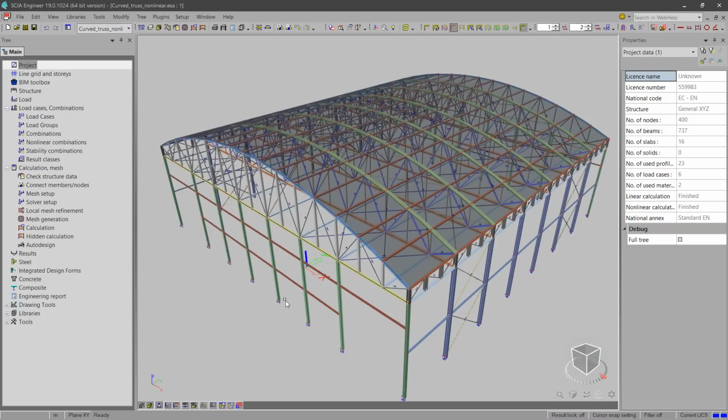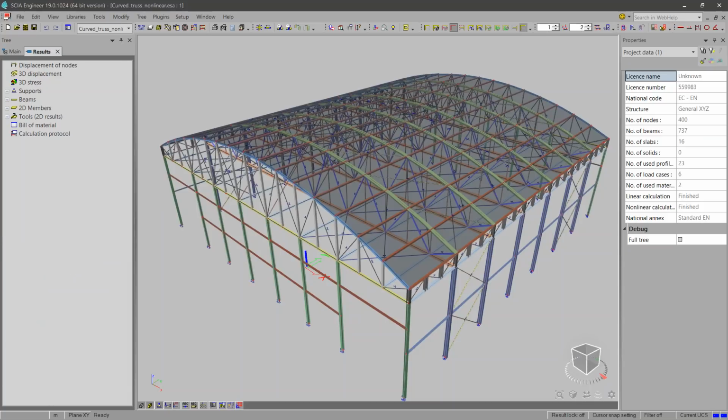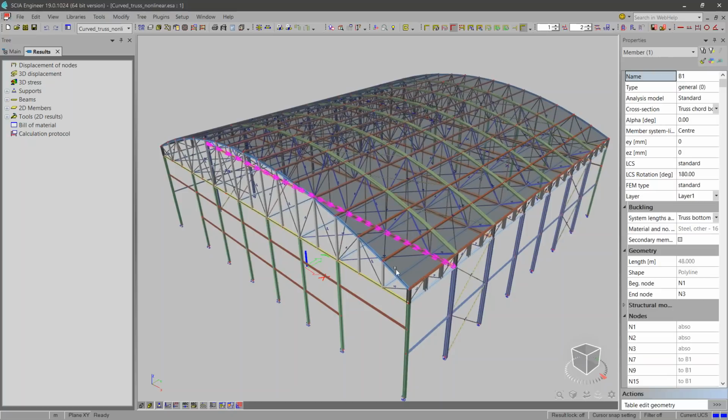So I have here this steel frame building, let's say not the most complicated, but a relatively standard kind of hull with trusses. And I would like to check its deflections. First I will talk about what you can find in the results service and explain a little bit the SCIA logic. Let's say that I would like to check the deflections on this lower chord of the truss.